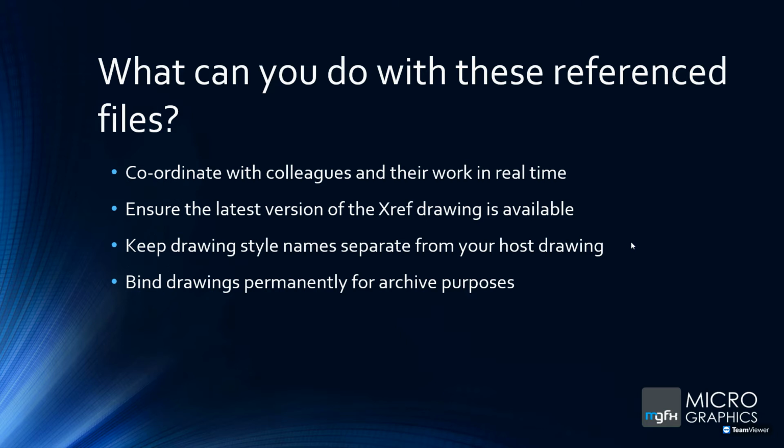Okay, so what can we do with these reference files? It allows us to coordinate with our colleagues or someone else we're working with on a project in real time. They make a change and click save on their file, and then your AutoCAD notifies you that there's a change in your Xrefs. Would you like to update it? And then you can go update it. So it ensures that we've always got the latest version of that Xref drawing.